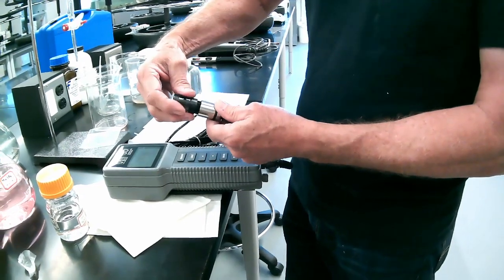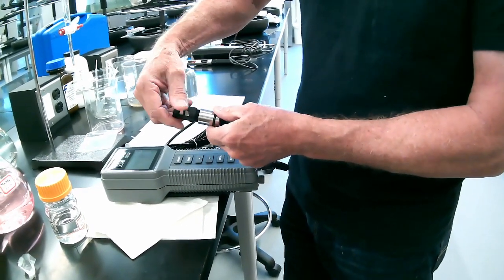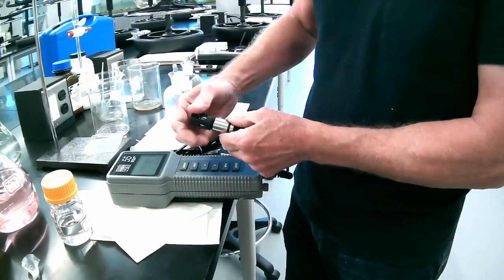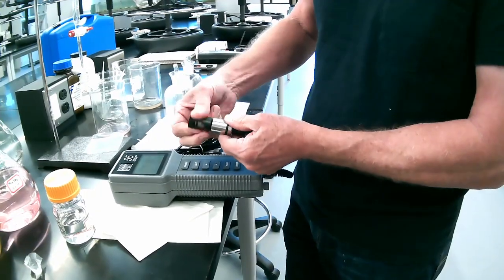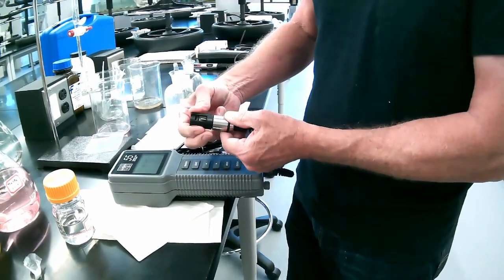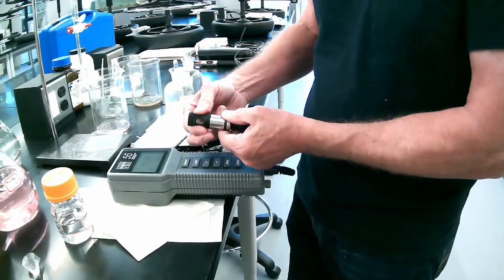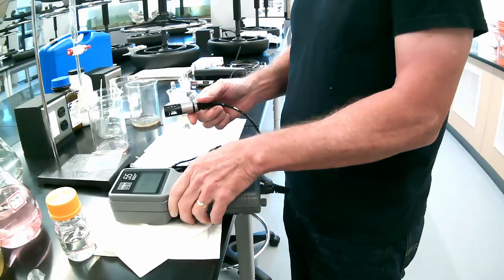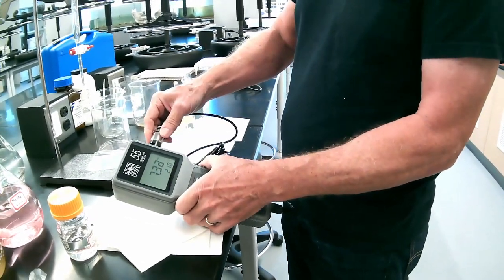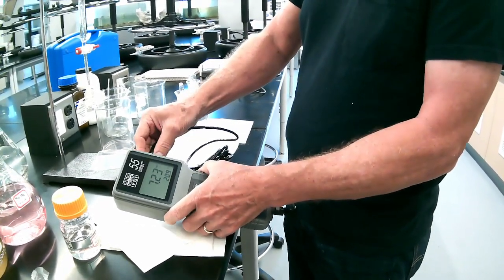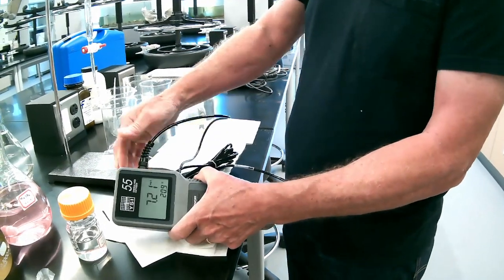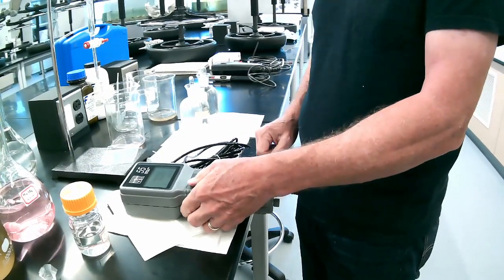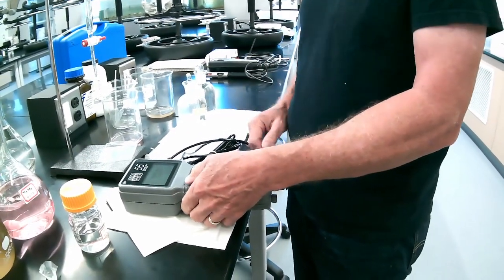Okay, so that's what we looked at earlier, and of course that was probably one of the more reliable ways of measuring oxygen, and we used these meters for a good 60 years. And I would argue, well, you can see I've still got one. Actually, I've got 5 of them upstairs that we use from time to time because they make really great field units. When you're done measuring the oxygen, you put this back into the little reservoir on the side, and we've got a wet paper towel in there, and that keeps the membrane saturated and extends the life of the membrane, essentially.